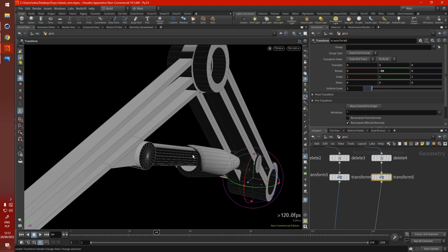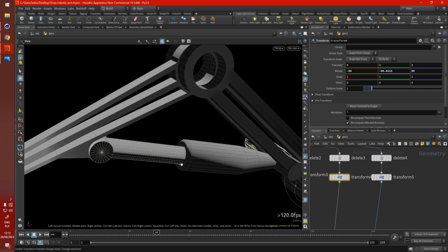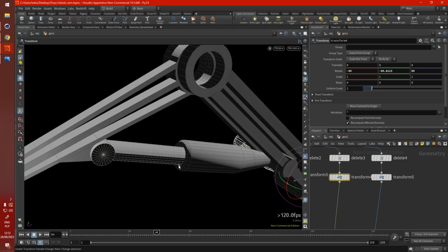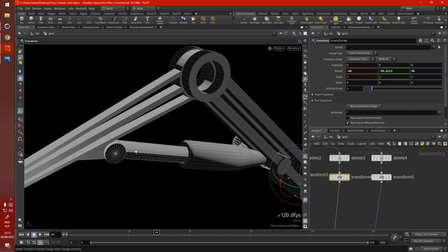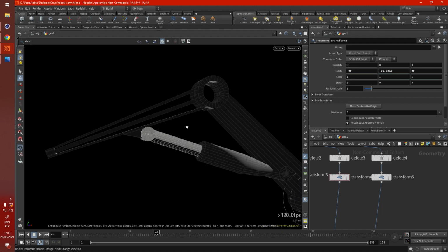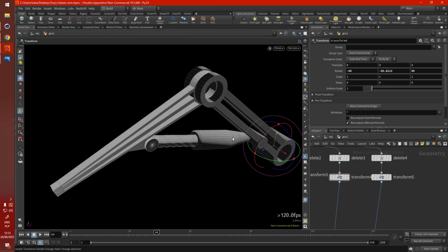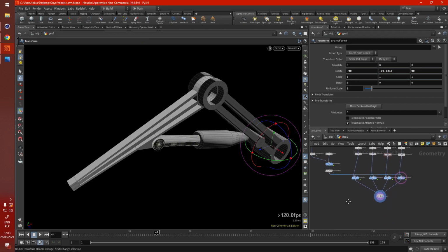You have to do it 50% this element, and 50% the other element, because if you do it just with one element, the other element is still going to remain bent, and if things are in motion, you're going to see that offset, you're going to see that error still persist on one side of the piston. So remember to balance it out. If 2 sides are off, then you have to balance out the 2 sides equally. You can't just balance it using one side.